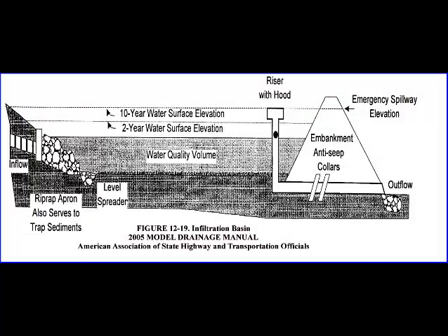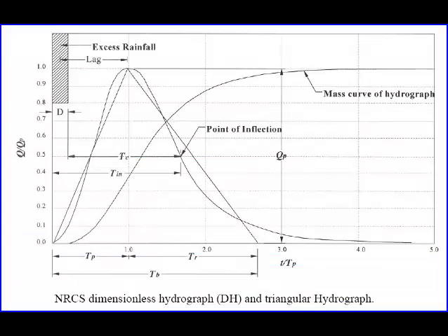Infiltration basins are not designed as extended detention facilities. As such, the program does not perform any reservoir routing procedure. The program provides the inflow hydrographs for the post-project conditions only. For retrofit basins with pre-development site areas and inflows, the hydrographs for existing conditions are also generated. For the inflow hydrograph, the program uses the NRCS dimensionless unit hydrograph.